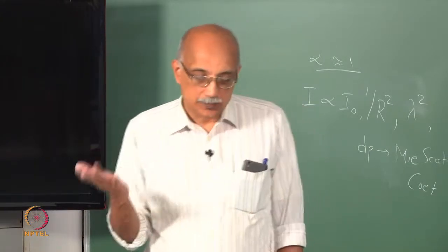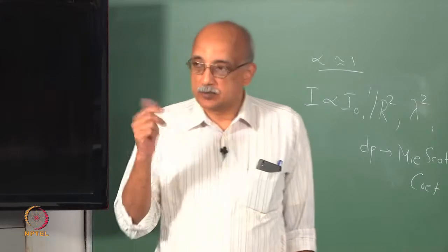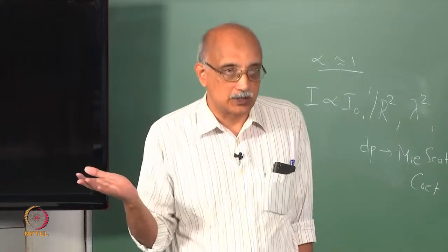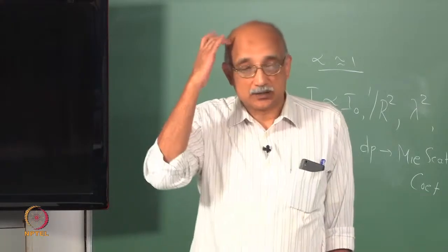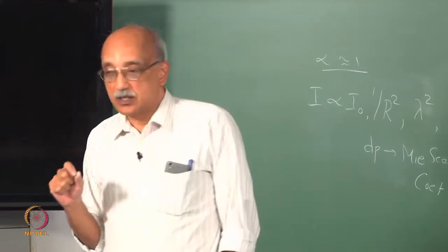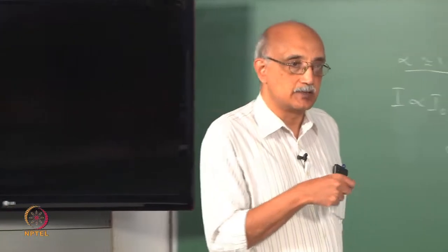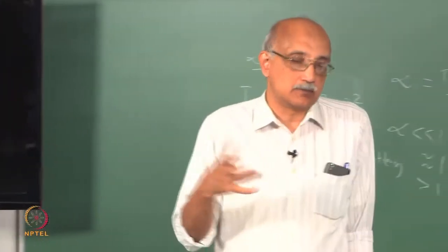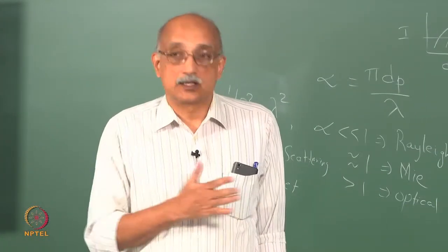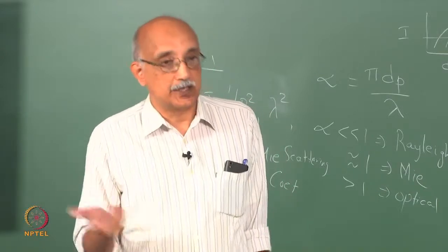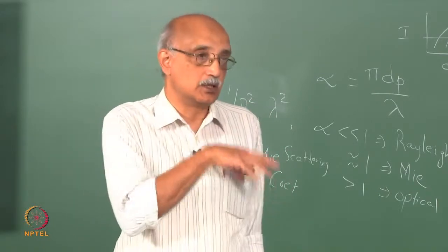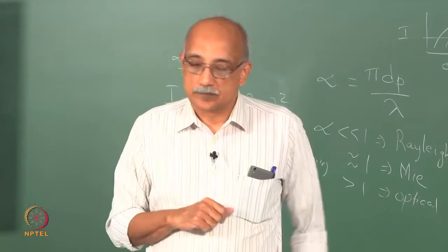Of course, with nano suspensions, if you wait long enough, they will become larger just because of natural agglomeration tendencies, right. But the size enlargement has to be done in a controlled manner if you want to be able to back calculate the original size before the agglomeration happens. So, you cannot let uncontrolled agglomeration happen and then try to estimate the sizes of the original particle population.